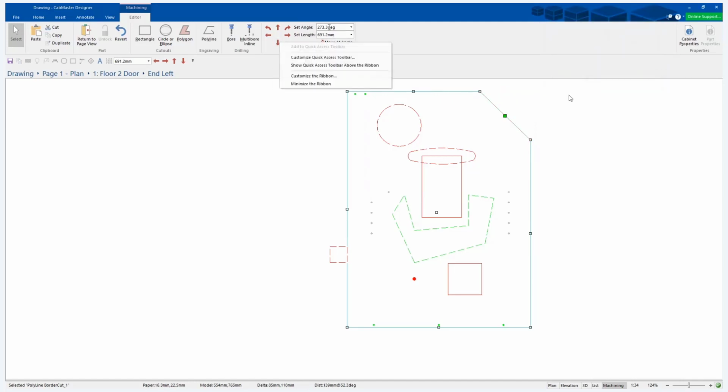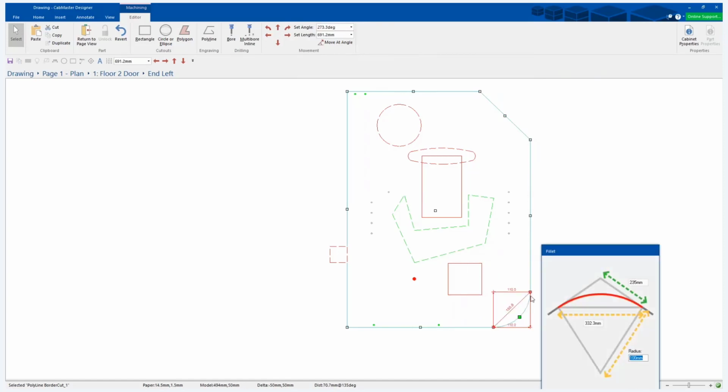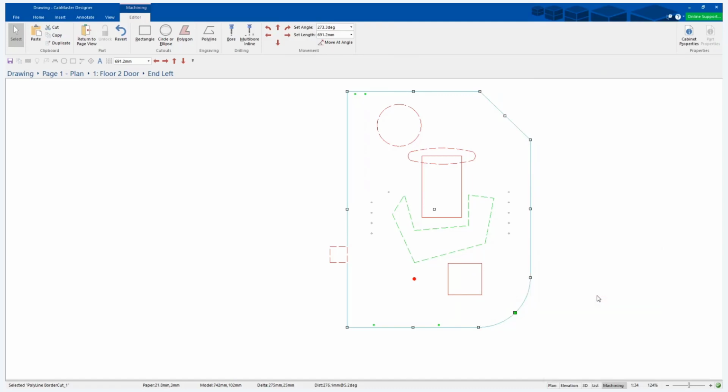You do have, where are they? There's another way to set the default numbers in here. I'll come back to that in a minute, because you can actually set default numbers in there. Same with fillet. Again, you can freehand it, or if you go over to it, sometimes it inverts itself like it's doing here. It doesn't matter because I'm going to say give me an 80 mil radius, and it puts it back into the right spot as well. So you can do different things in here. Tab to acknowledge it, and then hit enter to close the window down.